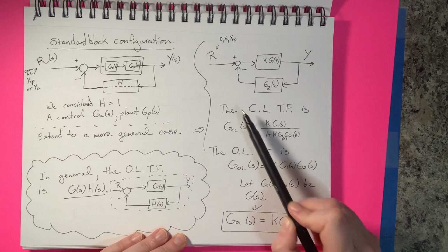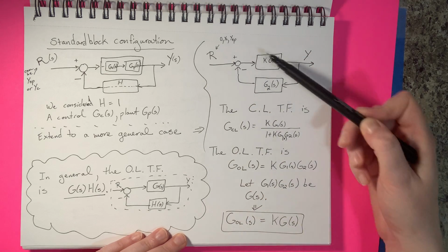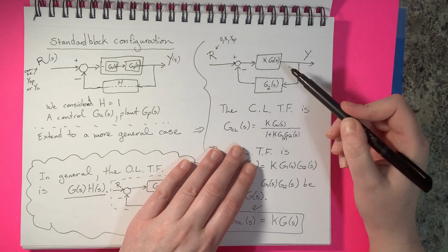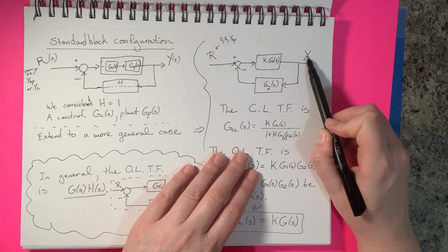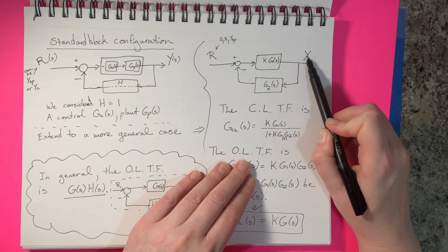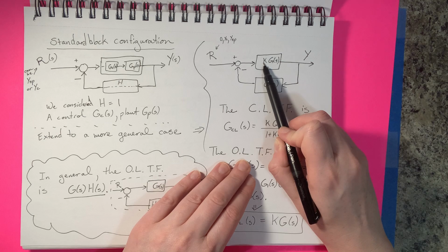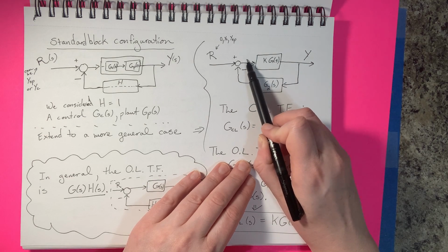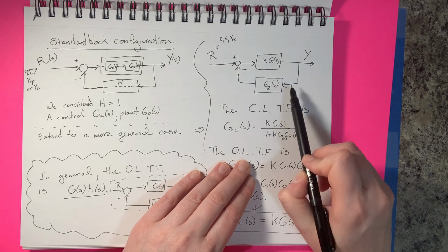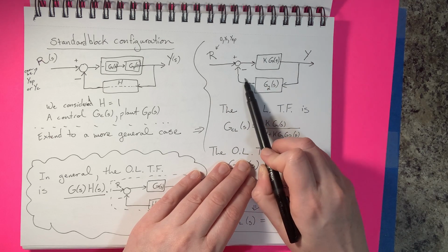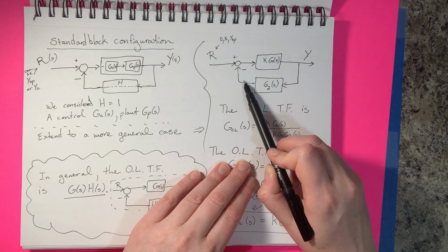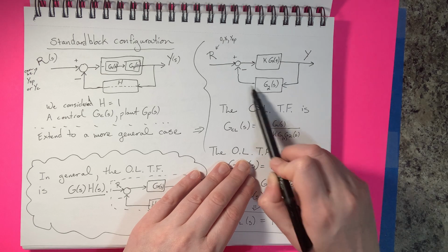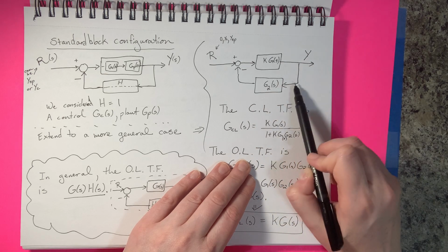We found the closed loop transfer function before. I believe we've done this example, but you just follow our normal line techniques to develop this by writing the line equation for y, which would be then kg1 operating on this line right here that you would have to label, and then the line here, which you again would have to label, referenced above, and that would be the output is equal to G2 times this Y input.